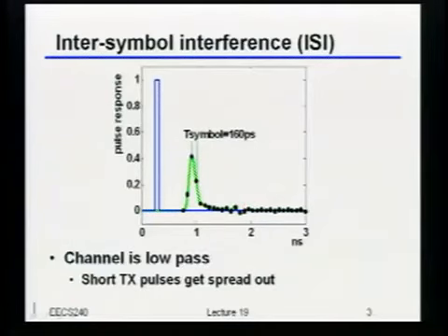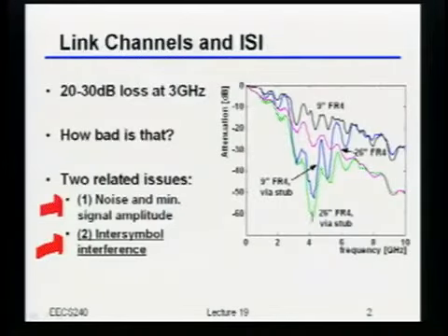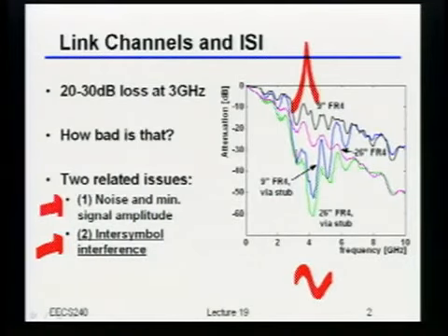And in fact, if you look in the frequency domain, when you see these things with a deep notch, that's a reflection. Remember, anything that has a narrow bandwidth centered at some upper frequency is going to look like that, because a spike up or a spike down is telling you either that frequency just doesn't make it through, or I'm amplifying things at that frequency.